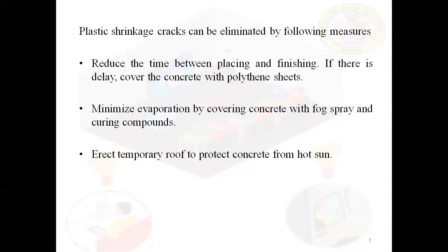Next, we have to erect the temporary roof to protect concrete from the hot sun. When it is in the afternoon time, we have to protect the concrete by putting some temporary roof. So by these three methods, we can avoid the plastic shrinkage crack.